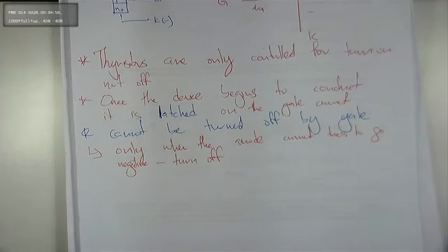So for example, if we are supplying DC voltage at the anode, I don't think the thyristor will turn off, because DC always stays positive unless you apply negative DC voltage. But if you are applying AC, you have continuous positive and negative, so it's easier to turn off the thyristor.